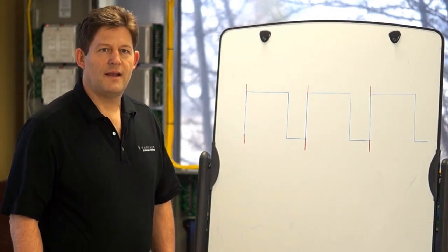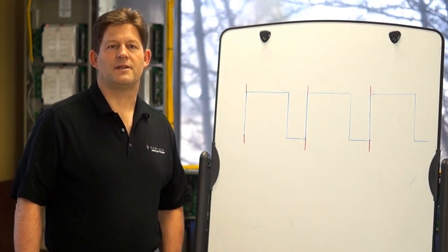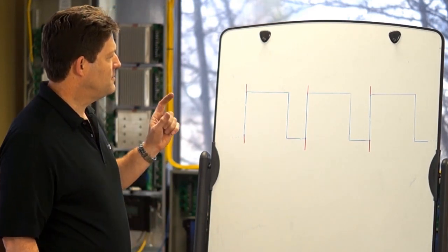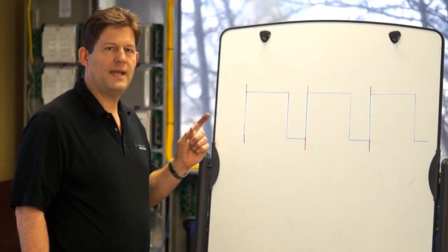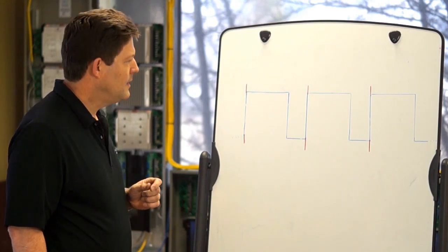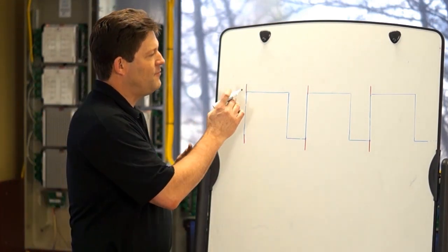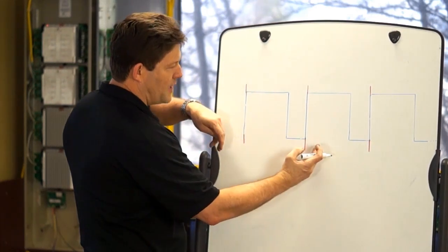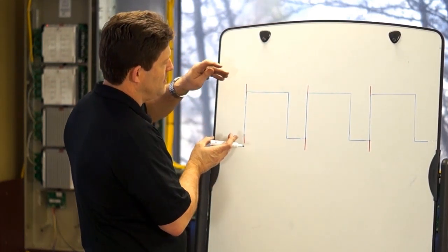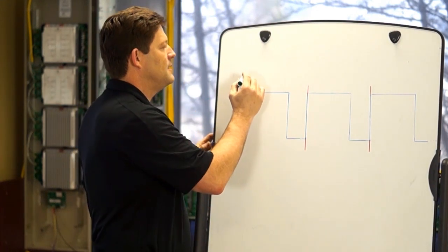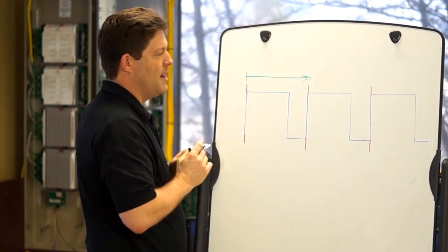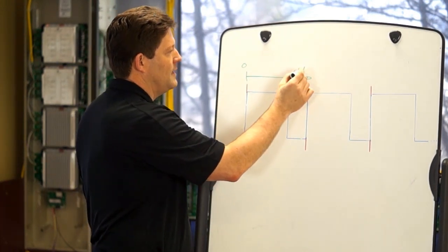A second method of analog indirect dimming is pulse width modulation, or PWM. In PWM, a constant voltage, repeating square wave is the control signal. Now, the percentage of the time that the voltage is on is actually the variable. We don't change the frequency, we don't change the voltage, we just change the duration that it is on. And that goes between 0 and 100%.